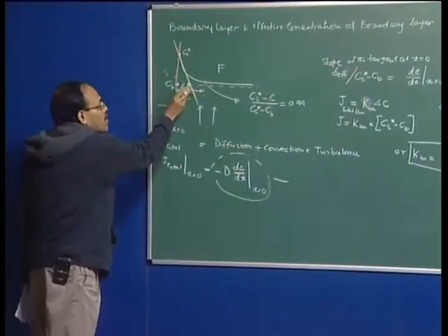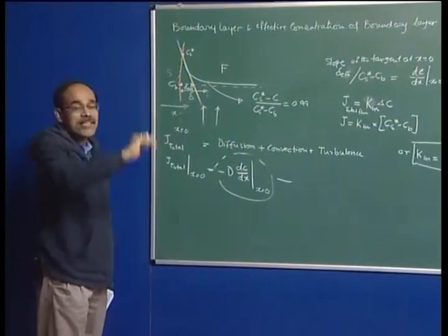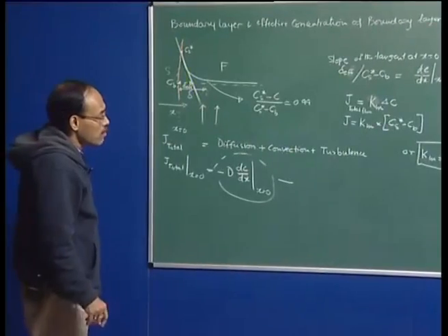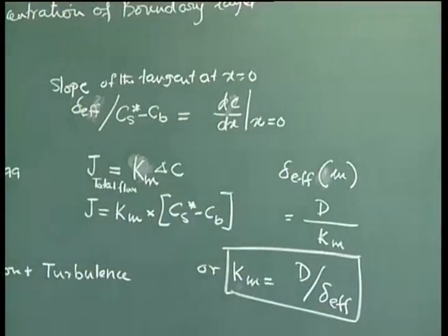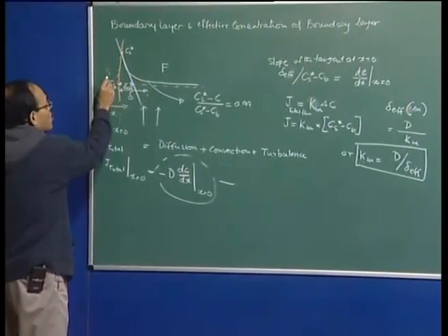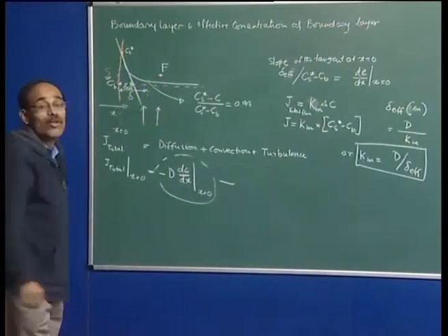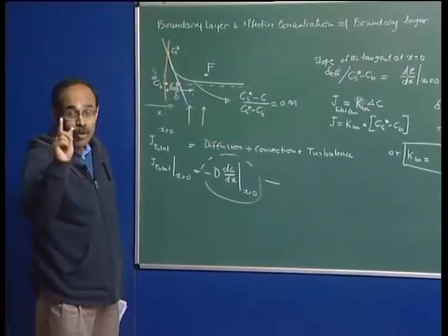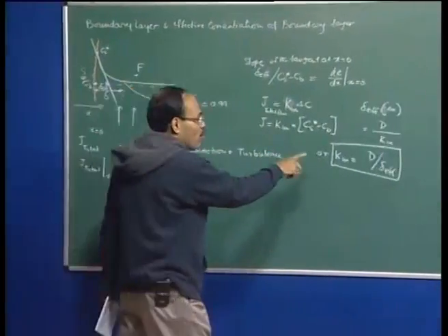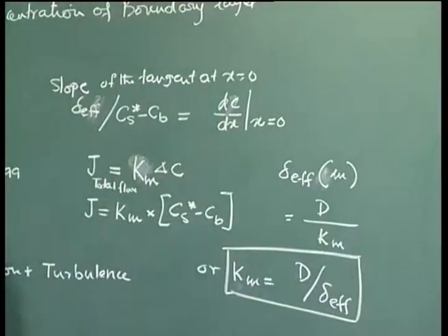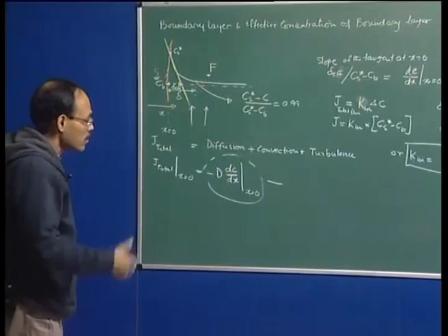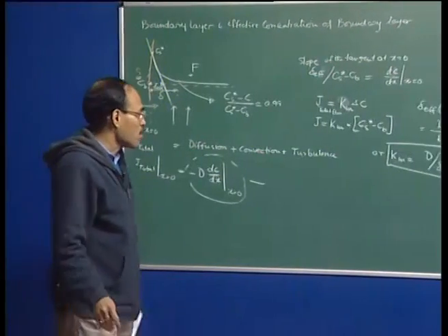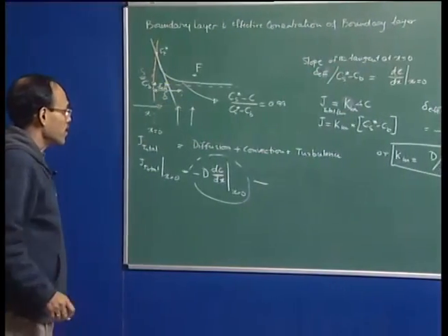which essentially means this distance will become less and less, provided the current of fluid past the solid is more intensive. And this is Km proportional to D to the power 1 when we are talking of mass transport between a solid and a fluid. But if you are talking of mass transport between two fluids, it is found that the mass transport coefficient becomes proportional to D to the power half, which one can show from Higbie's model, of course, which we are not discussing here. If you have taken any kinetics course or mass transport course, you already know this.